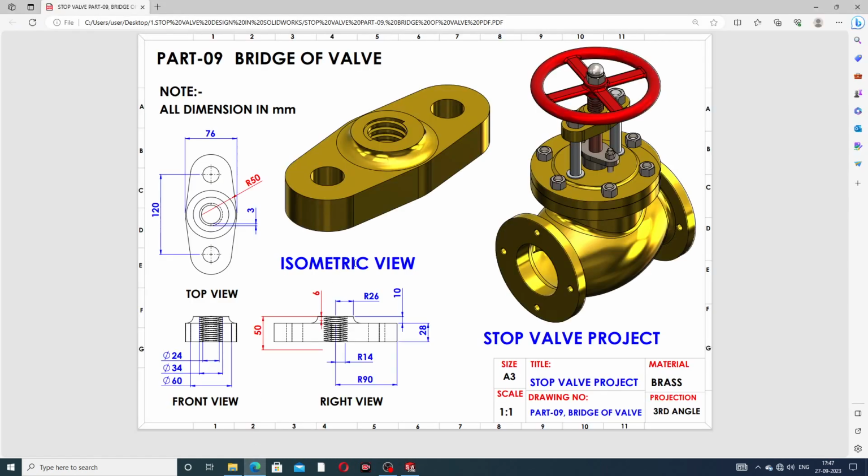At first, drawing this body with the help of the drafting. At first, draw this geometry. This distance is 19 mm radius, this distance is 14 mm, this distance is 28 mm, this is 10 mm, and this is 26 mm. This red color 6 is the revolution 6. This is the pitch, and this is the height and pitch, and height and revolution. This revolution is 6, this turn is 6, and this is a 50 millimeter height.